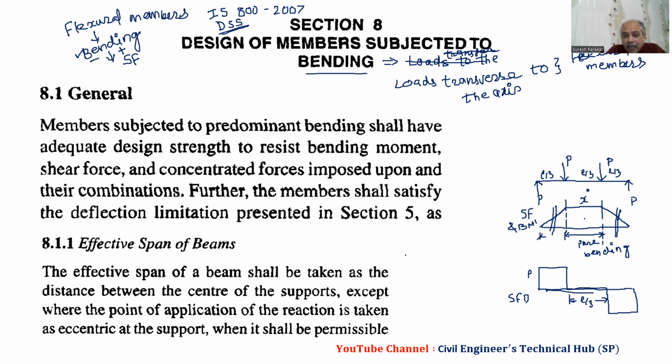Now if I draw a bending moment diagram for a UDL throughout the span, it looks like this. The middle portion is about L/3, so from both sides L/6, L/6. This middle portion is bending predominant.